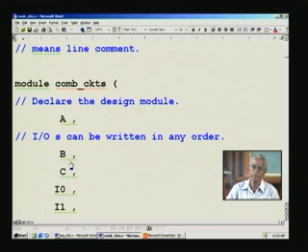And which order you mention is left to you. Whatever is convenient to you, you can do. It is rather a free format in Verilog. A, B, C can be an output, or one can be an input or output, or output and input. Any combination that you prefer you can have. So, it all depends upon your practice, right. And whatever practice you start with, stick to that, so that it is readable not only for yourselves later on after years of usage when you want to revise the design, but also for others who will be using your codes.